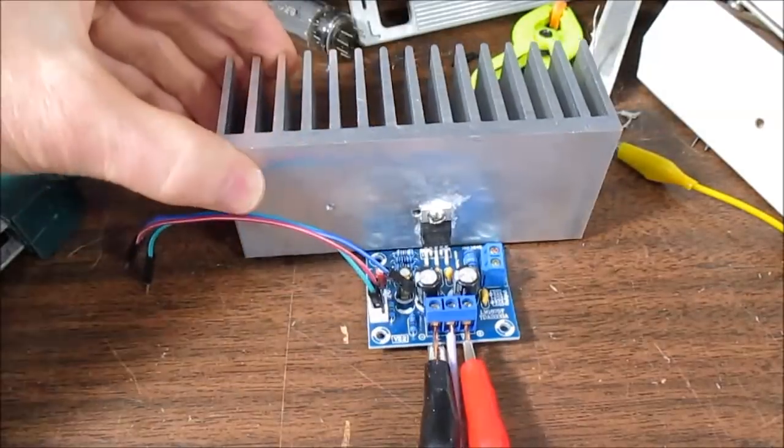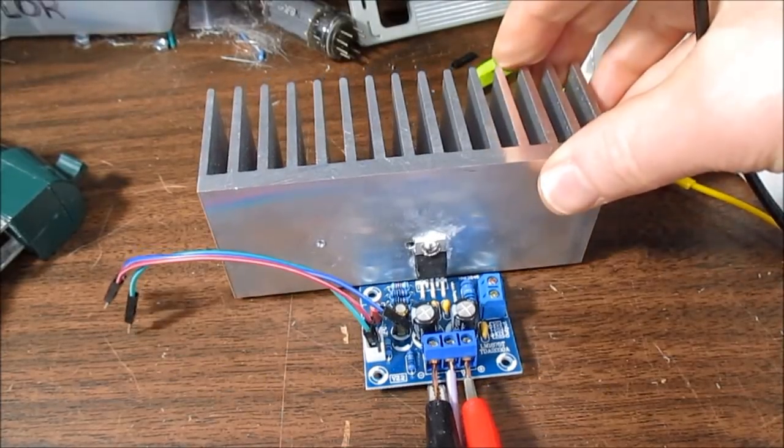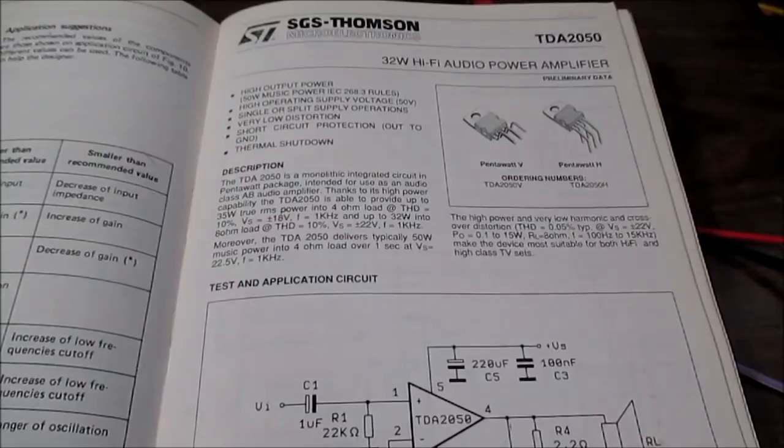Okay, now I found it. It was sitting on the heatsink, still connected to the heatsink from the video when I was demonstrating the TDA 2050. So now I can carry on with the subject of the video, and that is 10% distortion figures. Why do they use these silly 10% distortion figures? I've seen this question come up a few times, so I thought I'd answer it, do a demonstration, and also show you how you can get the real distortion figures of the amplifier.